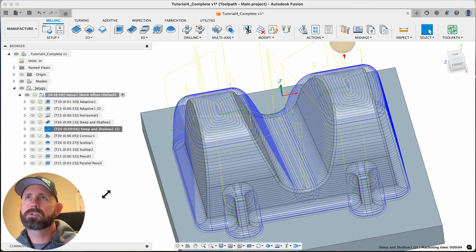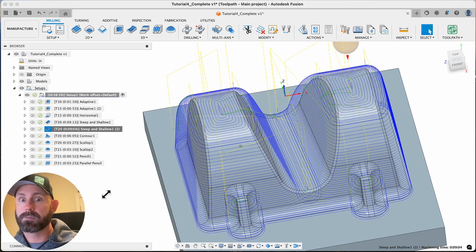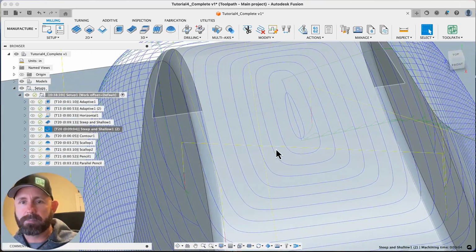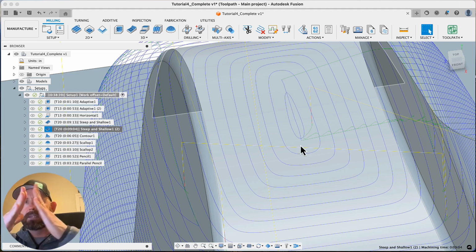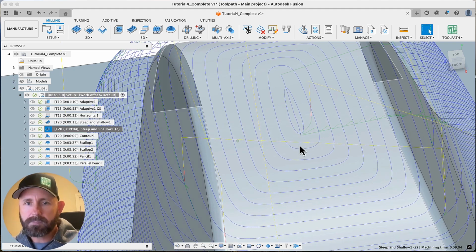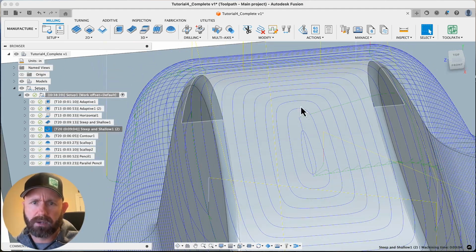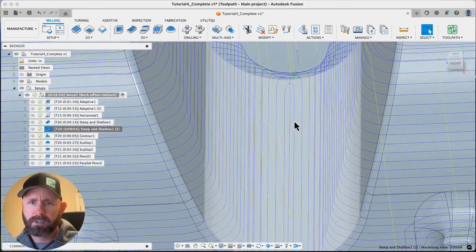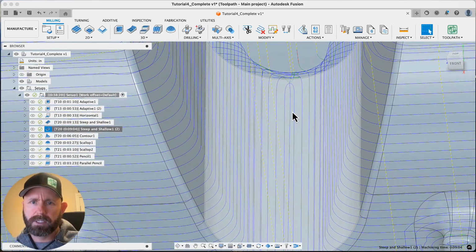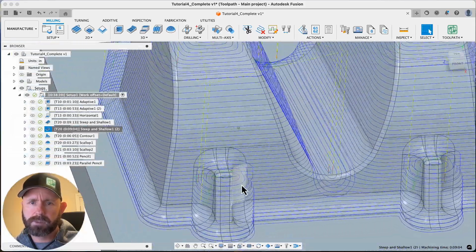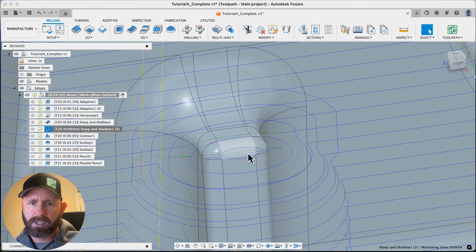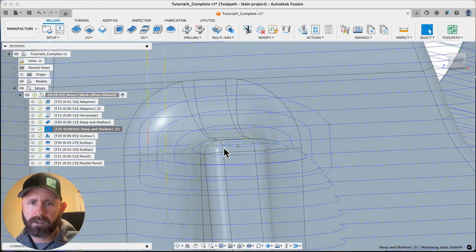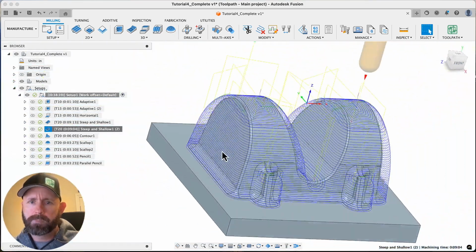And this is more prevalent with different geometries. Yeah, so as I predicted, it ran a toolpath straight down the middle of that to get rid of that little cusp. Sometimes you'll see it go out of these corners, which doesn't really make sense here with the curvature. And then it went right down the middle here, so it got rid of those cusps. It also got rid of a tiny baby cusp there, and it ran off there.